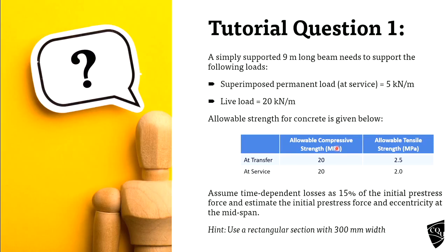So what we need to do is find out the pre-stress and the eccentricity. The question is to estimate the initial pre-stress force and the eccentricity at the midspan, and I ask you to use a rectangular section with 300 millimeter width.